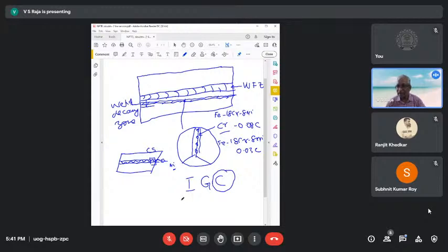For example, a chromoly steel can have intergranular cracking if it is, for example, what is called temper embrittlement, right? The temper embrittlement can lead to these problems actually. Sometimes the temper embrittlement can be compounded with hydrogen. For example, corrosion takes place, hydrogen gets into the material, and the intergranular cracking is now compounded by hydrogen. Okay, that is called intergranular hydrogen embrittlement, which takes place because of the tempered condition. So it can accelerate it. That depends upon how we visualize this. Yeah, there's no need for electrolyte there.